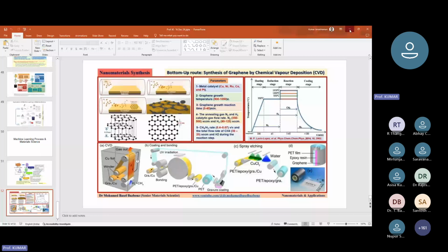But if you want it for large system applications, large power demand applications, then they are currently using copper indium disulfide or CIS cells. First Solar is a company which is producing cadmium telluride, as you might know very well because you have worked on cadmium sulfide. Cadmium telluride based substrates are used for these cells, and they produce very high current, which is very useful when you have a huge demand during the daytime.